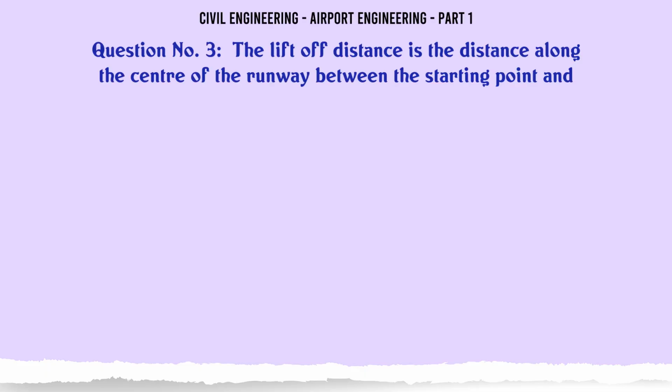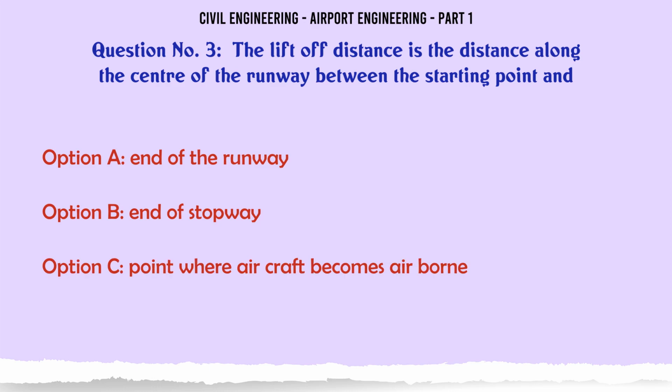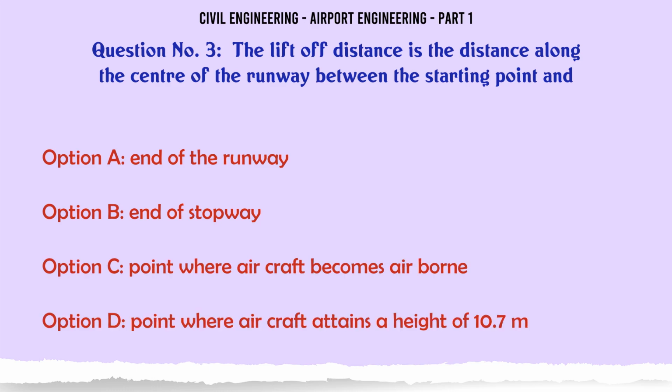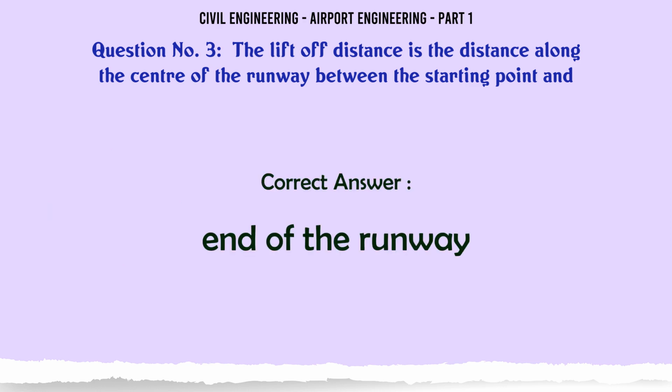The lift-off distance is the distance along the center of the runway between the starting point and A. End of the runway, B. End of stopway, C. Point where aircraft becomes airborne, D. Point where aircraft attains a height of 10.7 m. The correct answer is end of the runway.